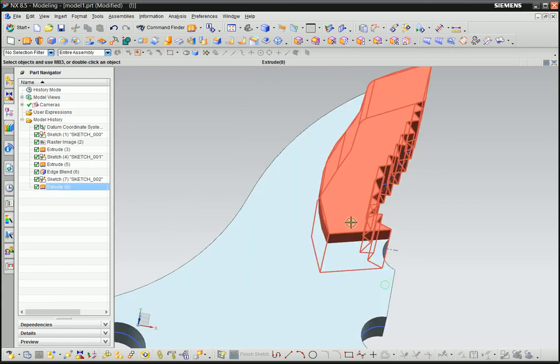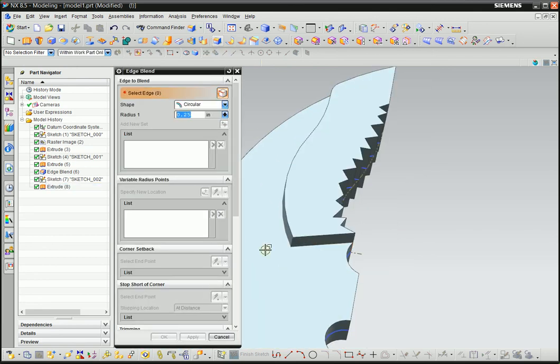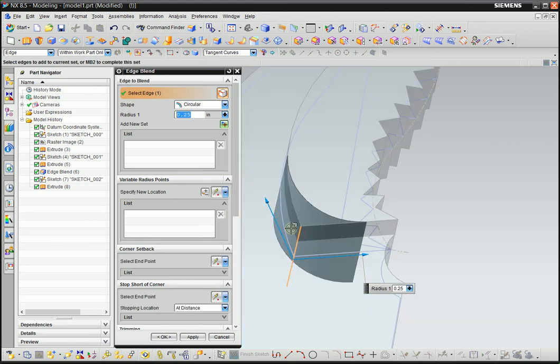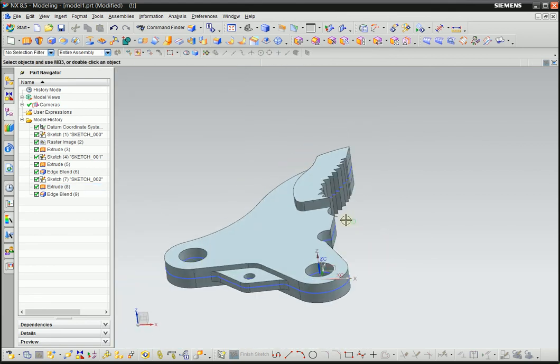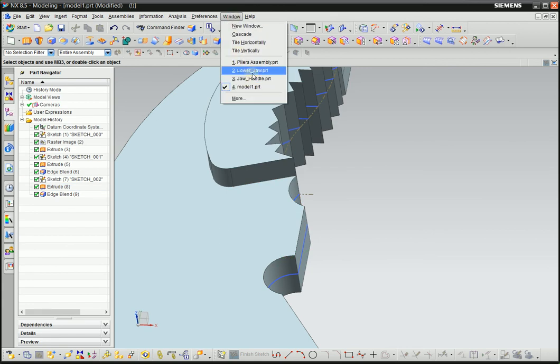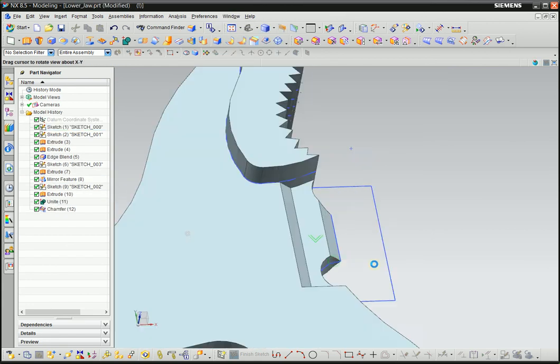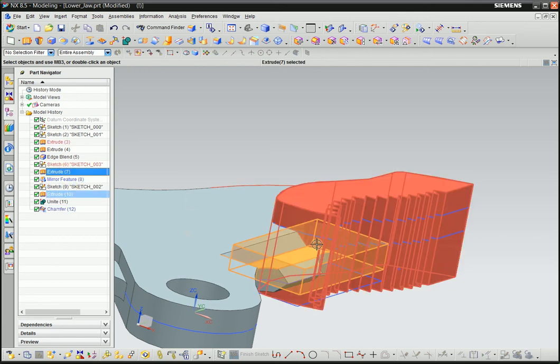Okay, and also when you do the curve, you can fillet this corner. So I can do also edge blend. Okay, edge blend, make this smaller. Click OK. Alright, now this cutting blade, as shown here, this blade, we can use Boolean command, use subject, and extrude something to cut the top geometry, something like this. Okay.